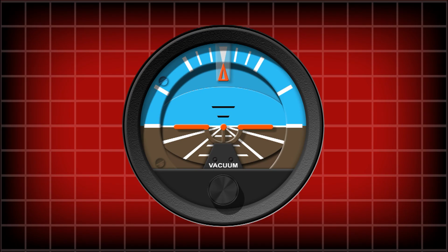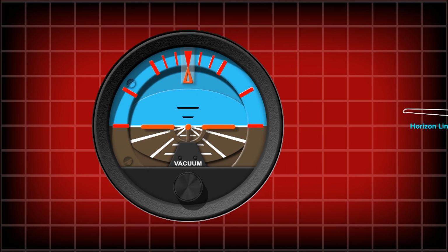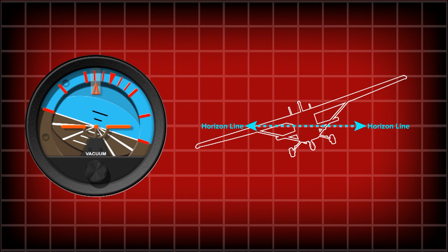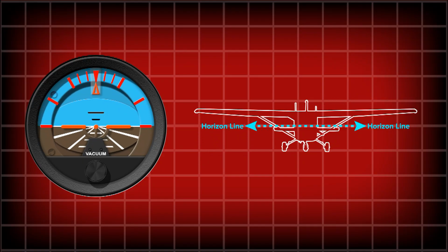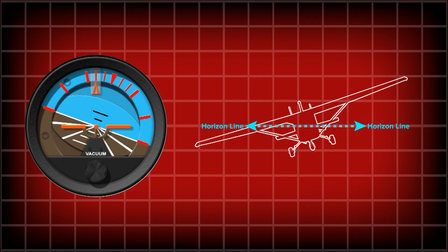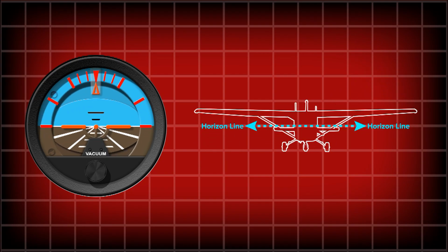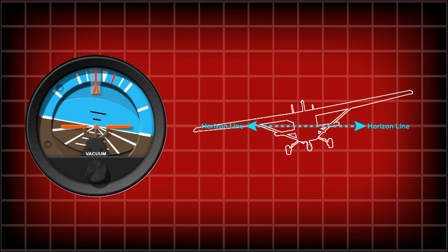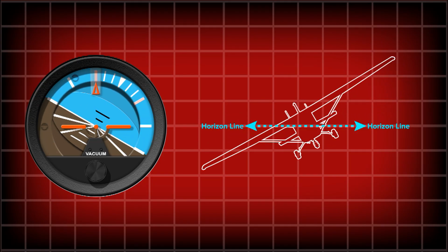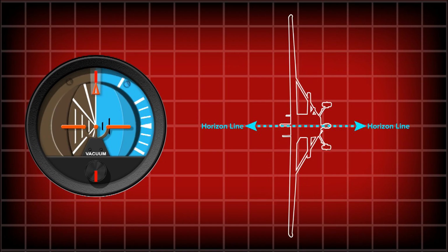Moving on, the instrument has a variety of scale markings. We will start with the markings around the circumference of the top portion of the instrument. These scales represent bank angle. You can quickly determine what bank angle the aircraft is experiencing when the orange bug rotates over that designated bank angle line. The angles that are represented on the instrument are as follows. These are 0 degrees, meaning the aircraft is straight and level. Then, banking to 10 degrees, 20 degrees, 30 degrees, 60 degrees, and 90 degrees of bank.